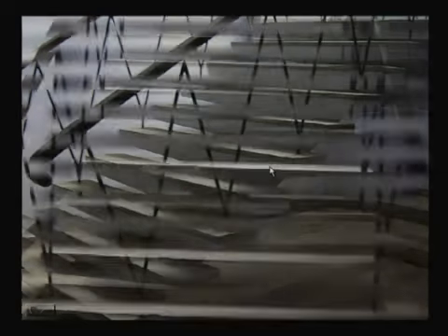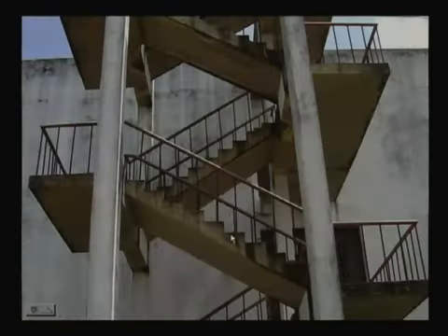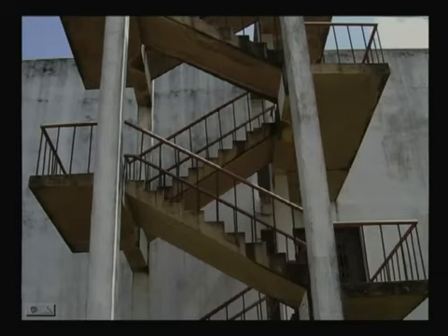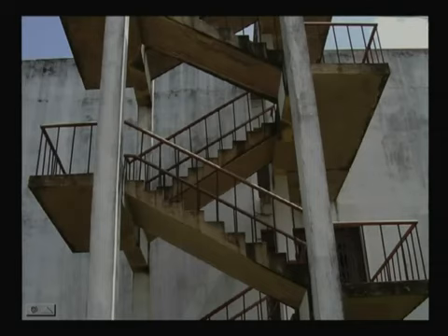But the most popular one, this is another view of it. In most cases you will find this type of staircase. This is the most popular one, and we shall design this one, but I shall also tell you how to design other staircases. For any staircase, what you have to do is find the governing bending moment, how it is acting and about which axis, and then design accordingly, as well as for shear force.